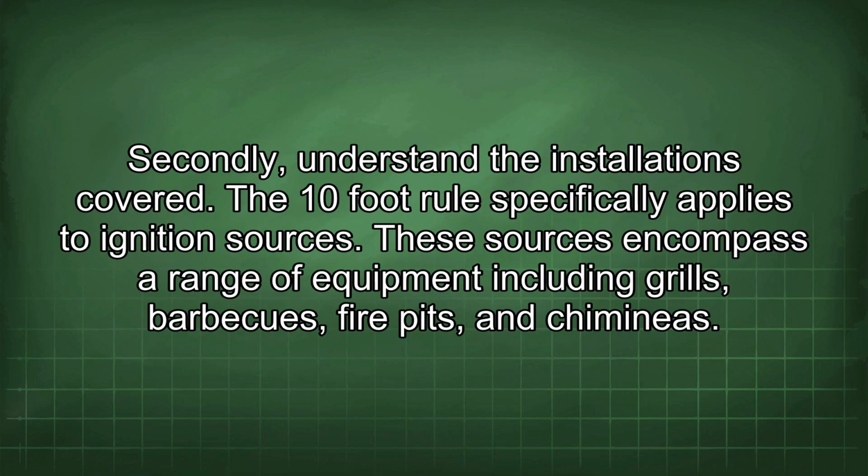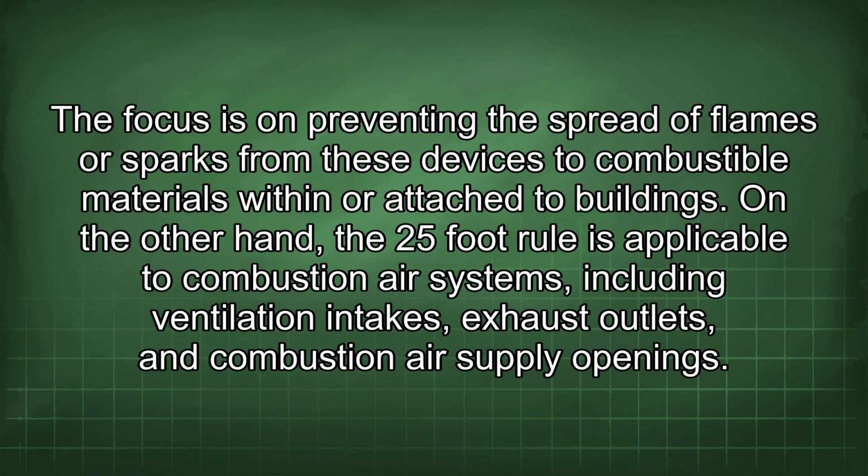Secondly, understand the installations covered. The 10-foot rule specifically applies to ignition sources. These sources encompass a range of equipment including grills, barbecues, fire pits, and chimeneas. The focus is on preventing the spread of flames or sparks from these devices to combustible materials within or attached